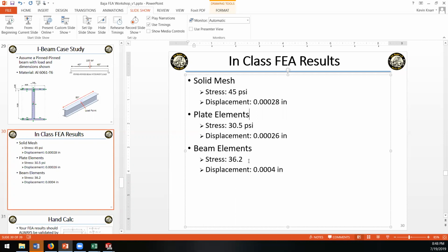Why do you think the bottom was so bad? I was expecting the top to be near the applied force, but I was thinking the bottom would end up being close to our end answer. I was surprised how far off it is. Yeah, I don't know. Most likely the constraint, because we have a constraint on the bottom. So it actually didn't go past the neutral axis, probably, because we constrained the bottom or something weird like that. Pinned. It was kind of like actually holding up those edges.